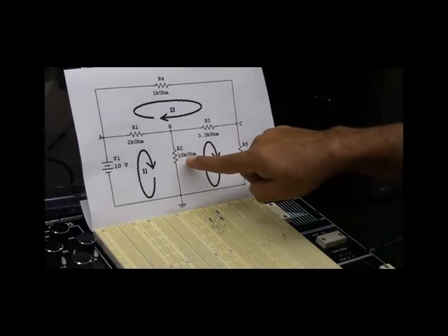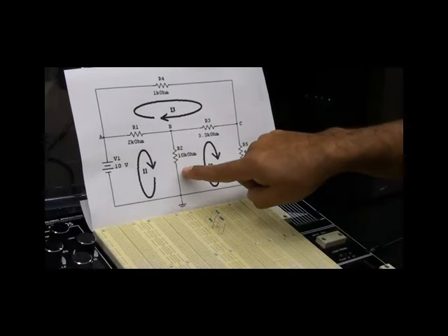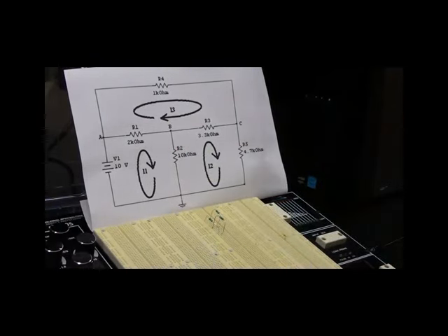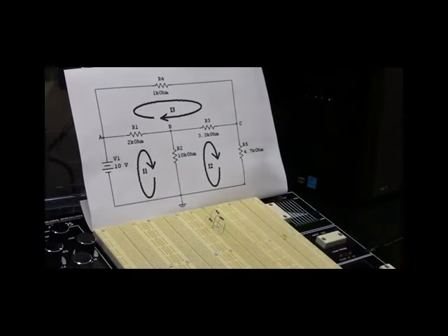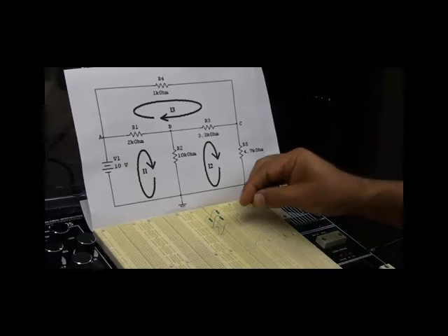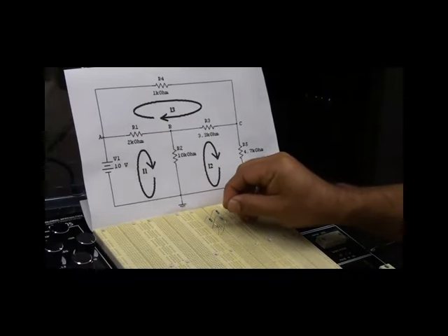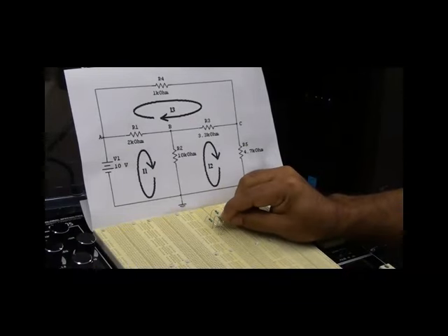Now it comes to the 10 kilo ohm resistor, R2, which is connected to the shared connection, point B, between R1 and R2. Where was that? This is the shared connection. So one side goes here.